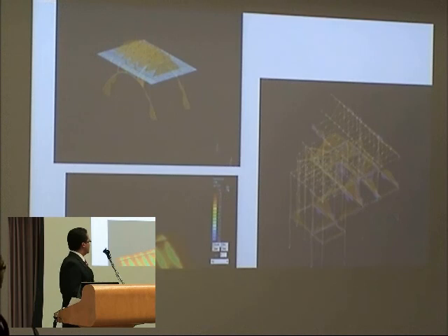Then we used the program to come up with basically envelopes of what the worst case scenarios were for each of these loads. In the case of the bridge, we actually had to simulate moving loads because the program that we used didn't have those capabilities. So we had to create different loading cases for basically simulating a truck being here, then at the next maybe moving a little forward and figure out which one of these was the worst loading condition. These were all backed up by hand calculations, which we used to kind of estimate what our loads would be if these were simpler structures.